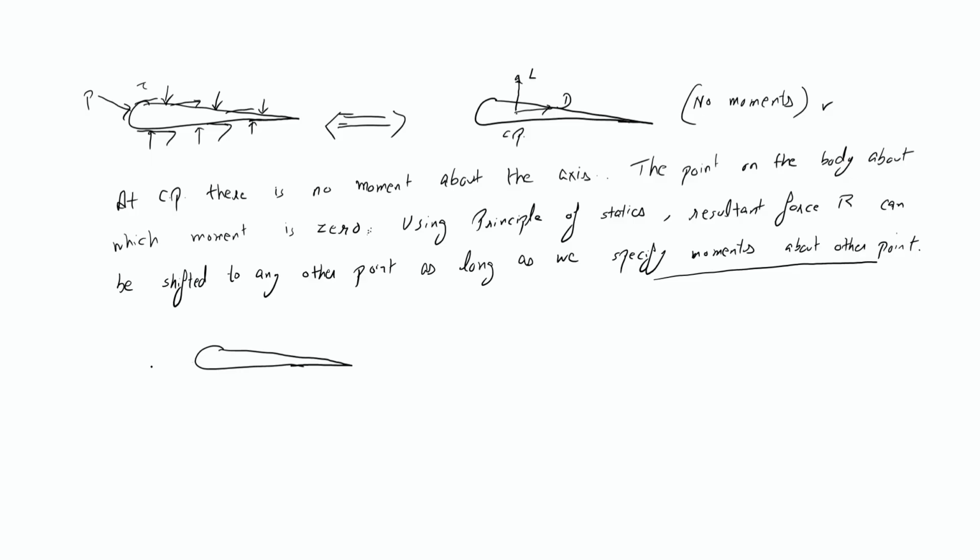Alright. So now we will consider this as the leading edge. Here we have lift, here we have drag, and this is the moment. So this moment will be the moment about the leading edge point. Alright, so this figure and this are equivalent. Similarly, we can choose any other reference point, for example, the quarter chord point.